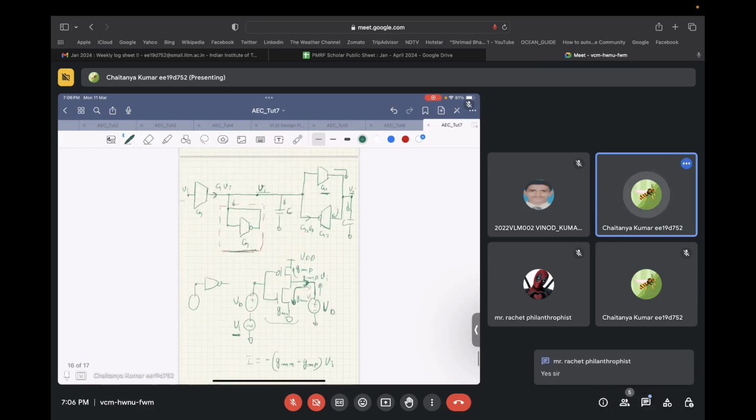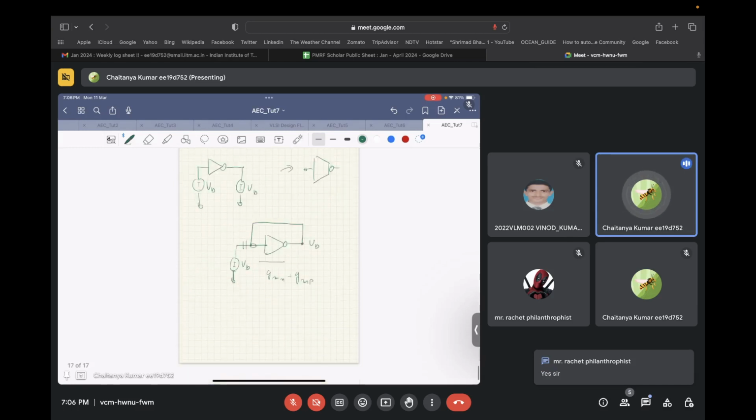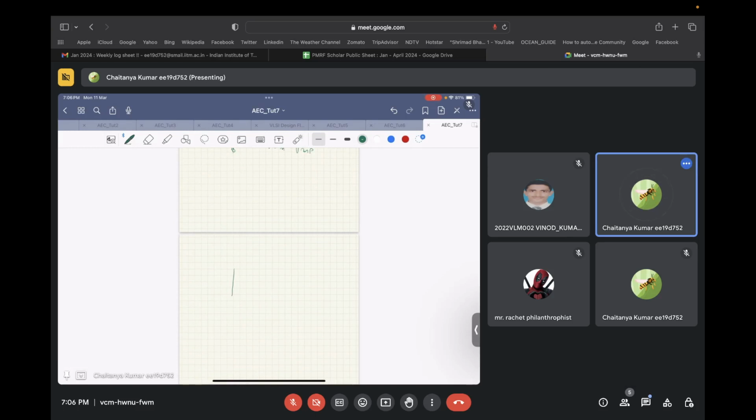Okay. So now we know that. So this part of the puzzle is complete. So we have this over here. This basically behaves as our conductance or resistance, and the quiescent voltage at the input and output of this transconductor is equal to VB.